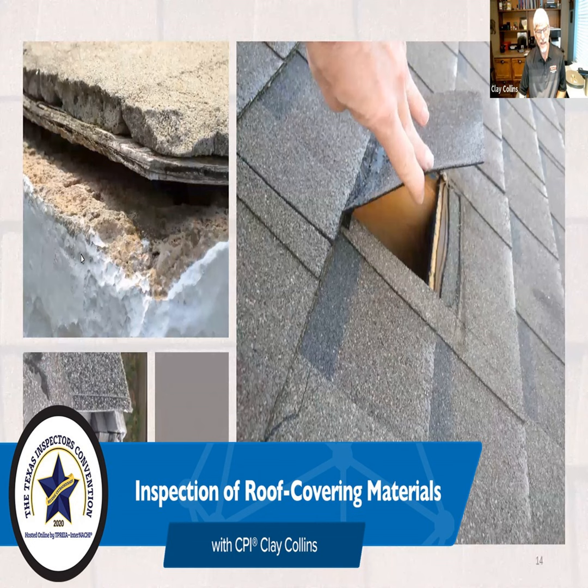I don't know of any roof manufacturer that says you can't use that type of material. The bigger problem is when that is insulated, when they put insulation up between there, whether it's spray foam or batting, and they don't allow airflow above it. It's the airflow that's more critical than whether or not you have the radiant barrier.